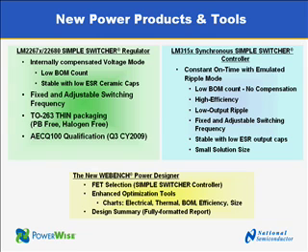Their advantage is very low BOM count, and they don't need any compensation. They are high efficiency. They have very low output ripple, although they are constant on time. They are available in fixed and adjustable switching frequency versions. They are stable with low ESR output caps, so you can use ceramic capacitors with these. And the solution size of that whole Simple Switcher controller is very small.